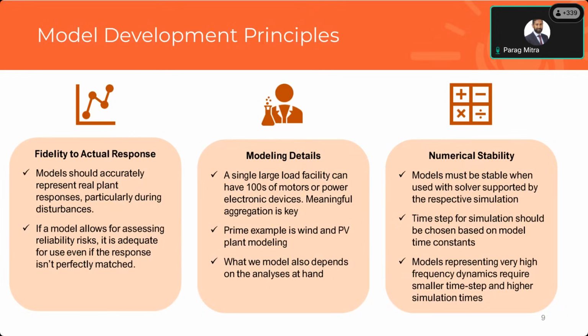Modeling detail, again, having a sense of what level of detail is needed for a particular type of assessment is going to be important. If you look at a large load facility, there's going to be hundreds of components within that. Like I said, if you wanted to model down to every single detail, the model of the facility could be as large as that of an interconnection. That doesn't help somebody if the simulations take a significantly long time to run.